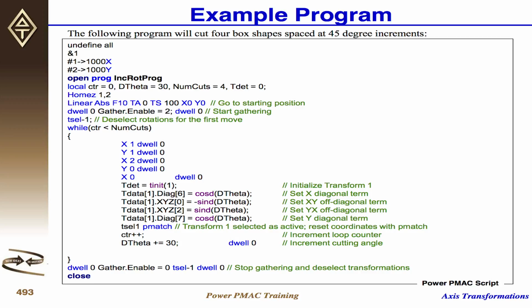Homing here shouldn't be necessary because before you run the motion program, you should home your motor. But here we have this because we don't want your motor to run all the way back to its home and start the program. So we start the program with homing, and then it will start right away.